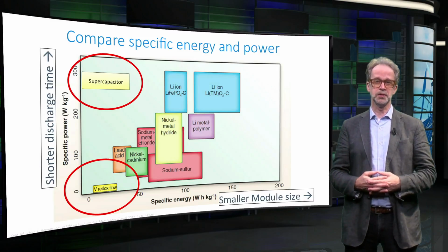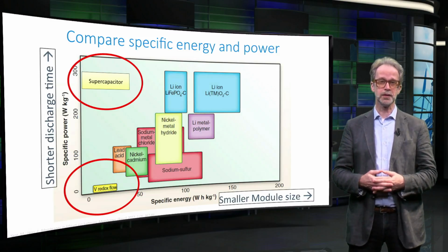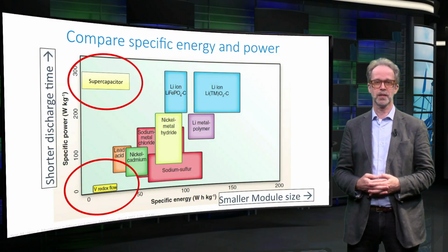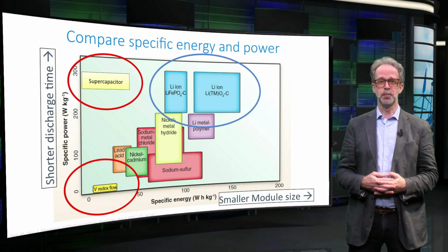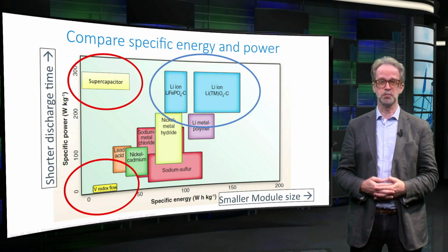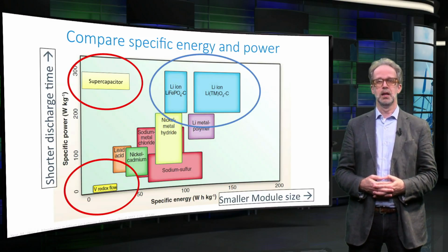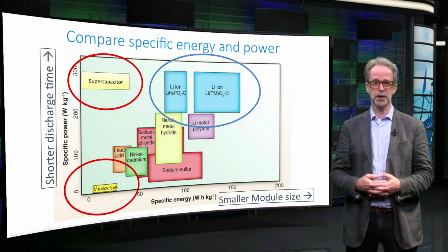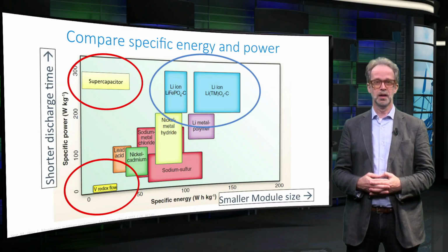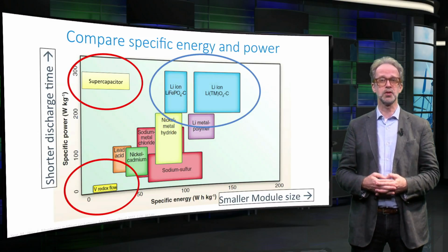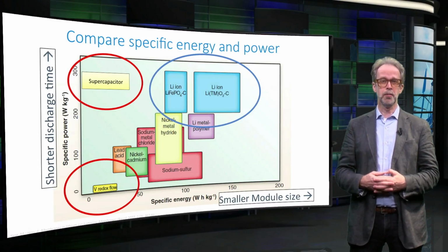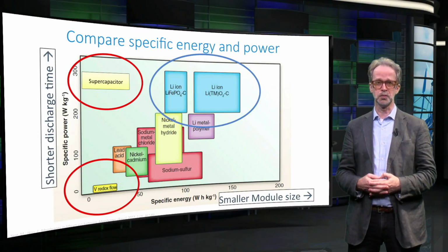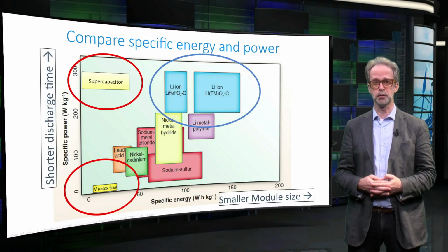The supercapacitor generates much more power due to the fact that the electrons may leave the capacitor plates at great speed. As compared to this, in batteries, more energy can be stored per kilogram of material. As compared to the capacitors, many more ions can be stored in the battery electrolytes. This is due to the fact that the ions are charge compensated. Remember, however, that even in batteries, the storage capacity is limited to around 100 to 200 Wh per kilogram.